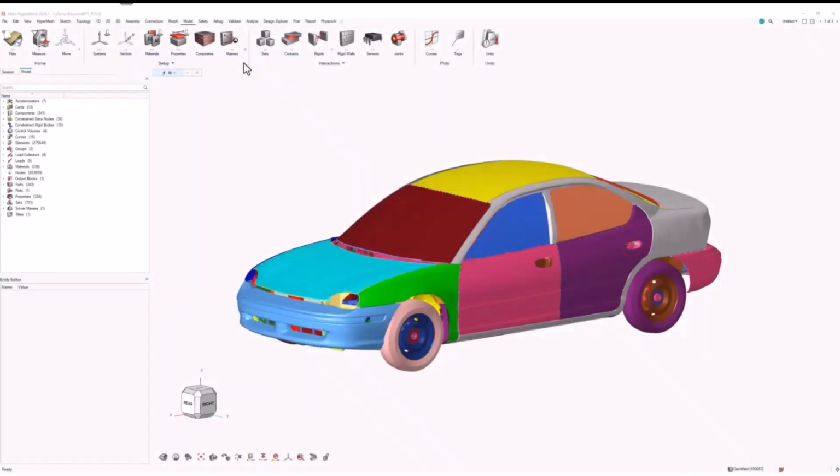I have prepared two recordings to show you the workflow here. For example, starting with LS-DYNA. Here you see the choice that you have between nodal and part mass type selection. You can also activate the display option for COG, and in case of the nodal mass, you can also activate the nodal mass distribution at the end of the workflow.